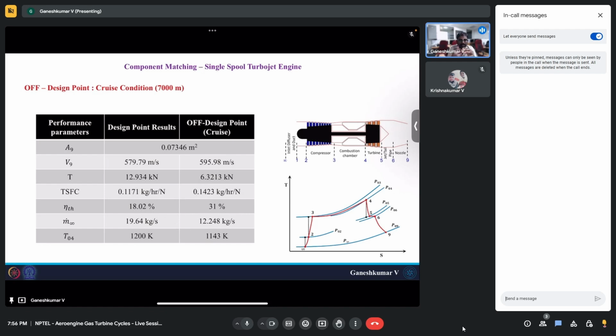So here we can see, both in design point and off design point, our pressure ratio was almost the same. Both were 5 only for now, but ideally your pressure ratios will be different. Because when you couple the N also, and you also take into account m dot, which will be varying because of A infinity. M dot infinity will vary because of A infinity.